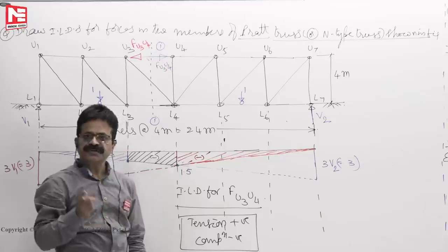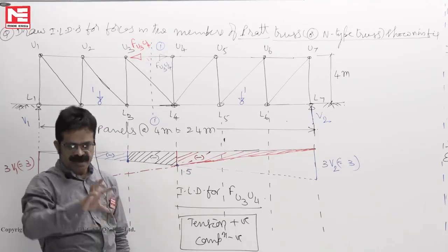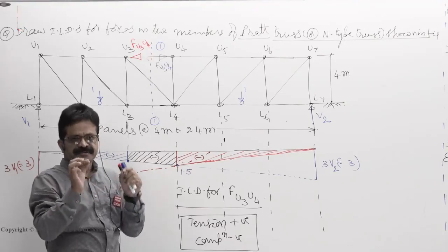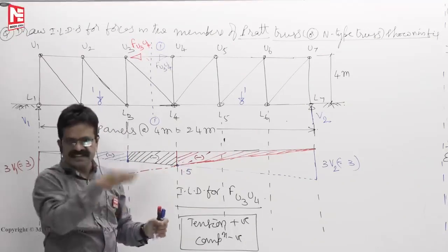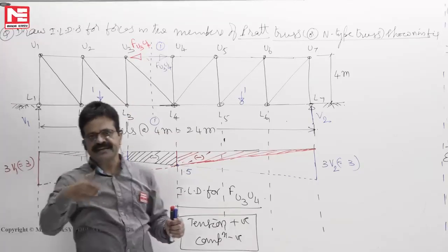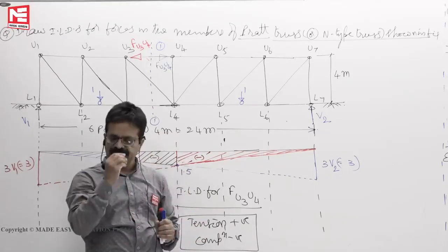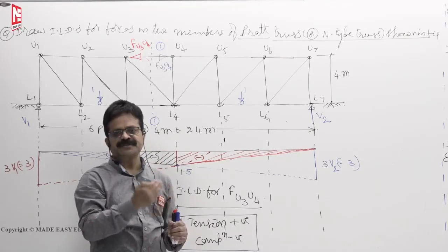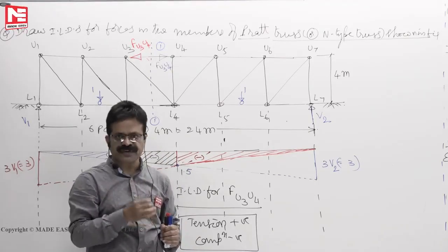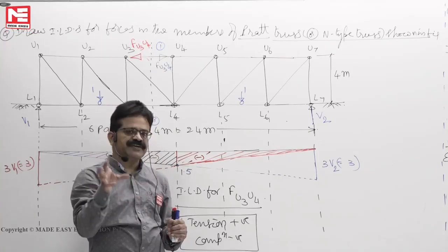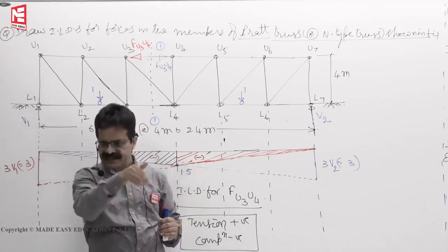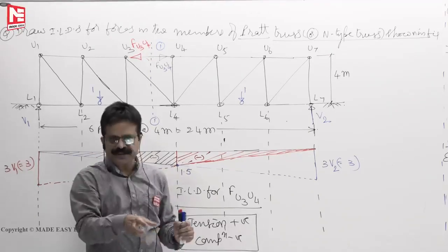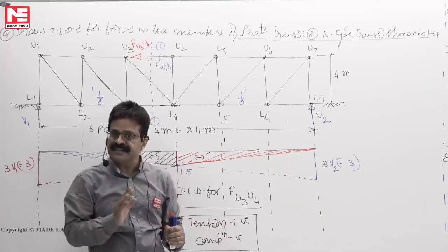Such graphs we have drawn in strength of materials also. Mohr circles you have drawn. You have a small element subjected to Fx, Fy and shear stresses. Then on a plane at 30 degrees you want to find the normal stress. Then you have one formula: (Fx plus Fy) by 2 plus (Fx minus Fy) by 2 cos 2 phi. Now phi value 30 degrees means 2 phi is 60 degrees, you will calculate. I don't want 30 degrees, I want 35 degrees. Then 70 degrees you have to put, again you have to calculate and waste the time.